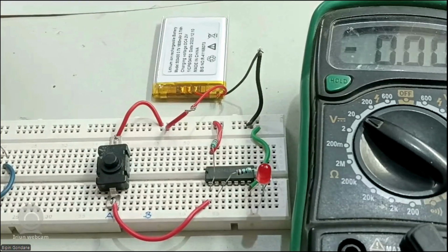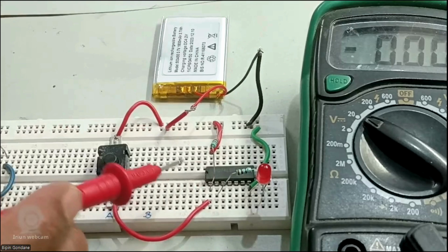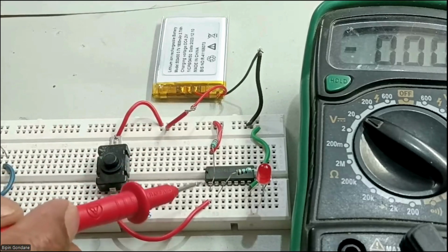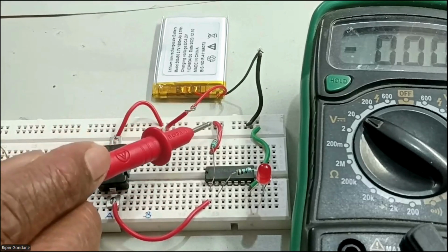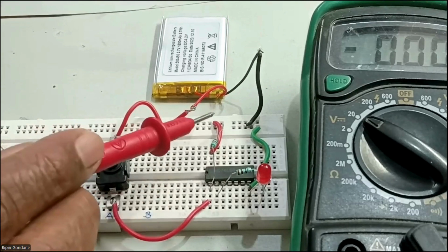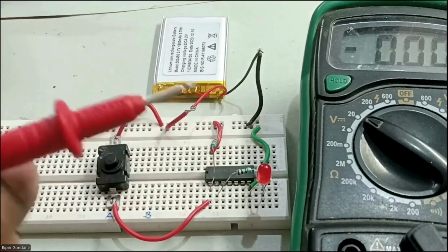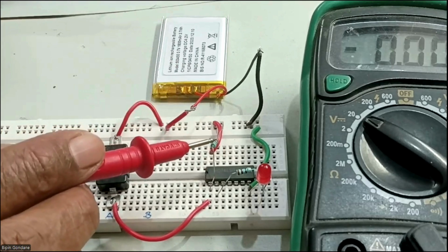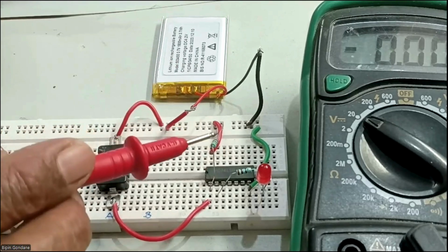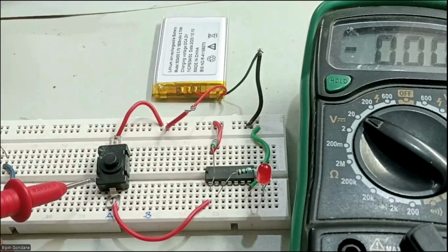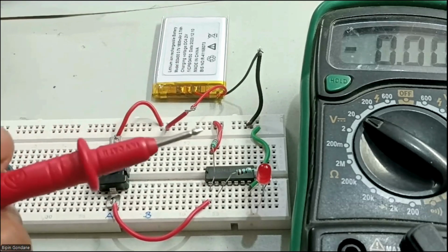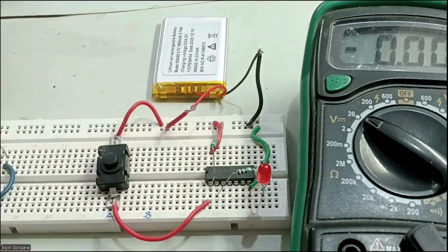I hope you understood this circuit. The IC numbers you have to understand. Again, here at the input I have connected a 10 kilo ohm resistor to the supply. Everywhere you have to remember 10 kilo ohms. Whether it is one input or 2 inputs, you have to connect this resistor of higher value, 10K, compulsorily. The only difference is that we have used only one switch with this gate, because there is only one input. I hope you understood.